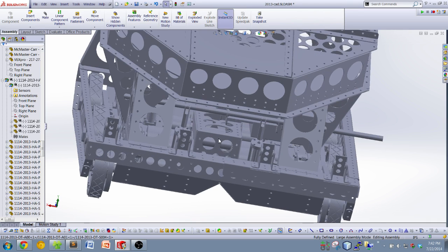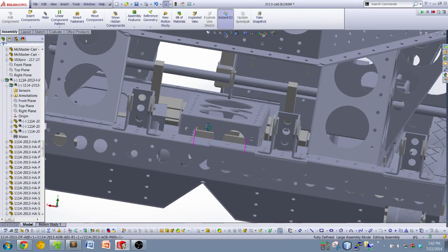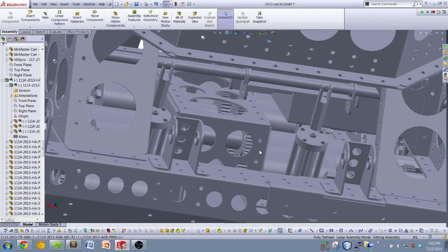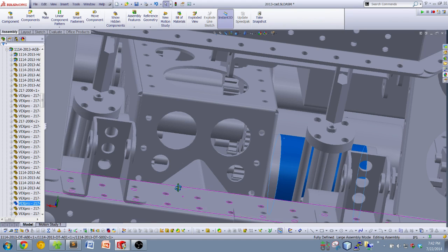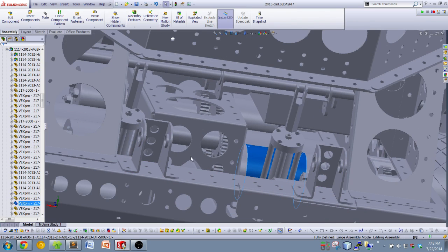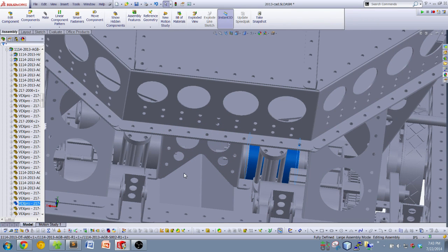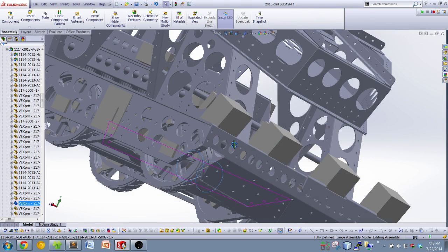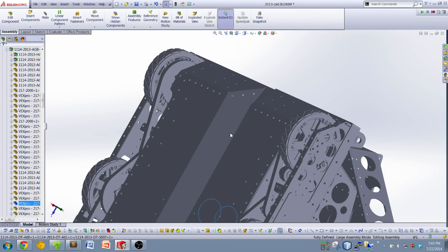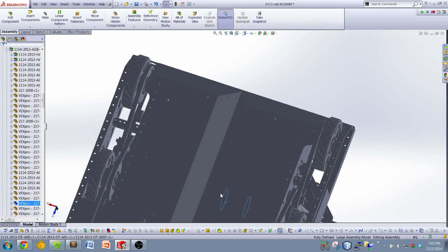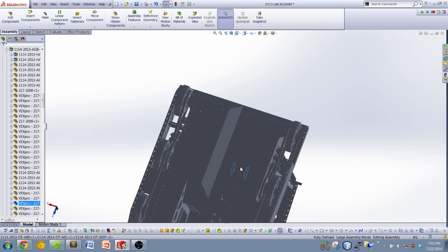So it's a little tricky to get into because it's not all sub-assembly, but basically that telescoped out. These motors back here pulled basically a winch that pulled it back in, and it was able to pivot up and down. It had pneumatic cylinders that moved the whole thing up and down to bypass the little knuckle on the pyramid. Their whole chassis underbelly was cut with this V so that it would glide up the pyramid, and it had Delrin along it so it would slide real easily.